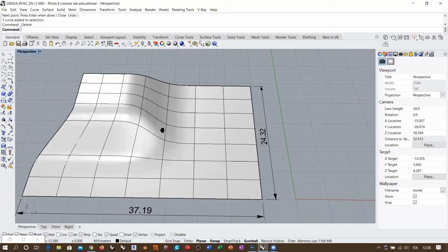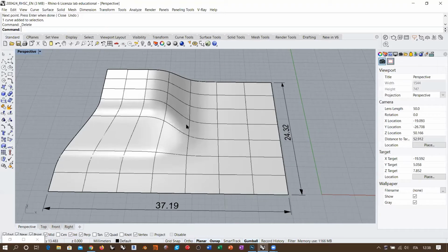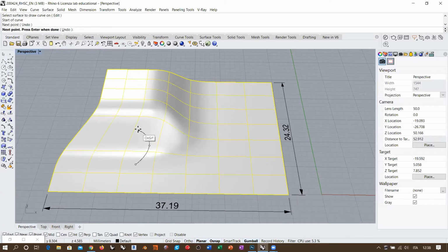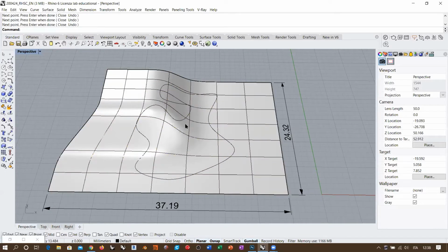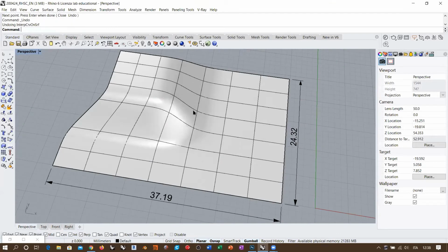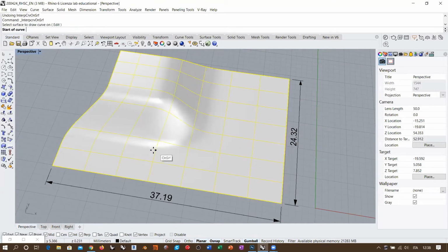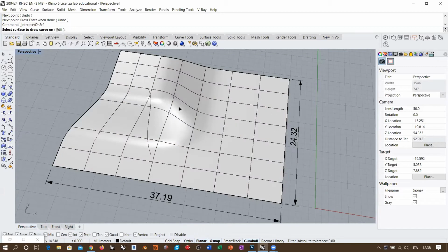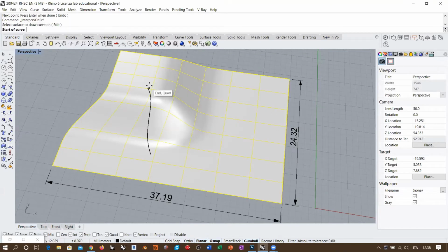For example, if I want to create a curve with vertices using this technique, I cannot do this with one single execution because the points are always smooth points, okay? Because this is an interpolated curve, right? So I cannot create vertices. In order to create vertices, I need to create, for example, one interpolated curve and then execute the same command another time. I start from the endpoint.